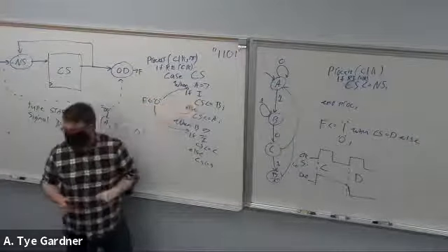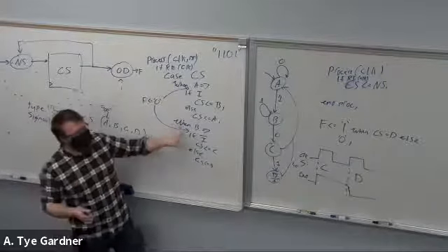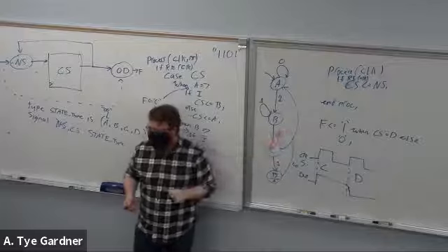Now, I don't like doing that because these if else statements can get like if this, else if this, else if this, else if this, right? And they can get really long and it gets really tedious. That's why I'm a big fan of the output decoder being its own thing, as combinational logic. Really big fan of it.